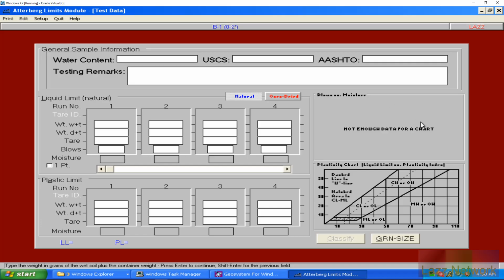Okay, I know for most newer versions, I don't think this is tab. This one doesn't seem to be tab friendly, so it's probably going to be enter friendly, I'm assuming. So let's put in our liquid limit values. I got 28.28. Oh, good, it is enter friendly. 25.70, which makes sense because the newer one is the same way. Whoops, that's not an enter. All right, and then blows is 32.